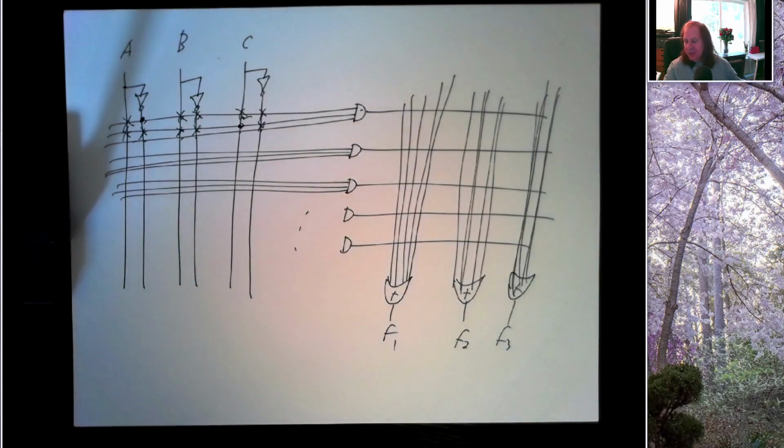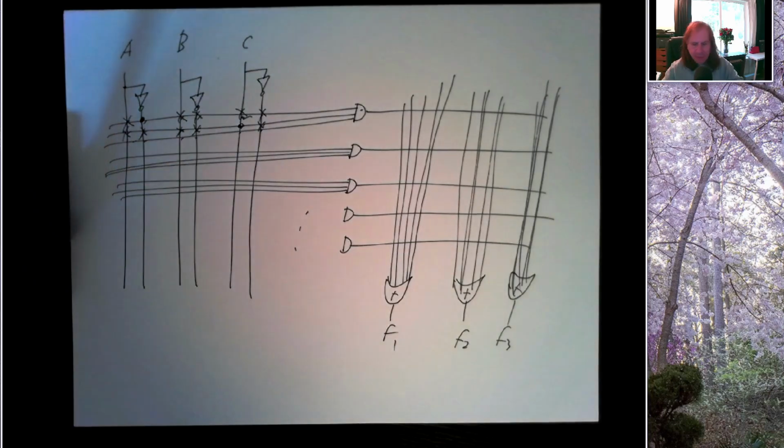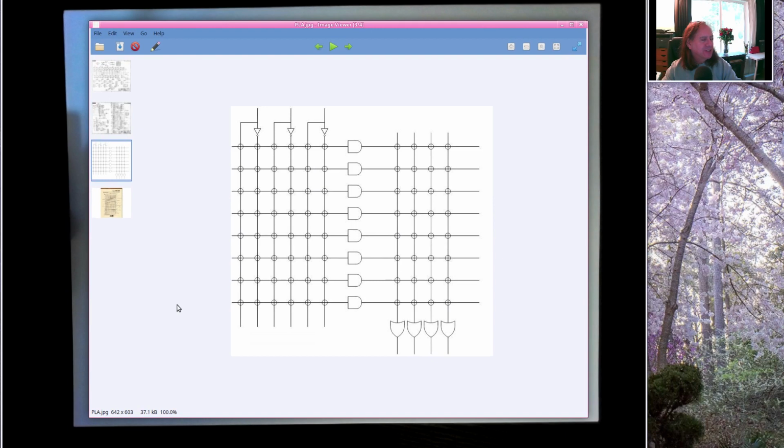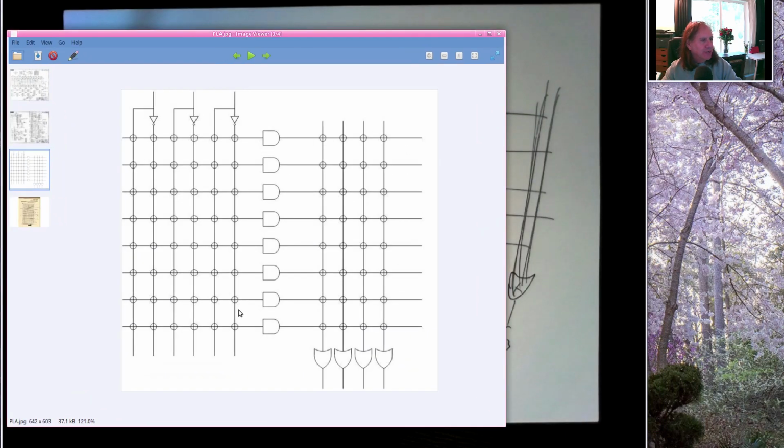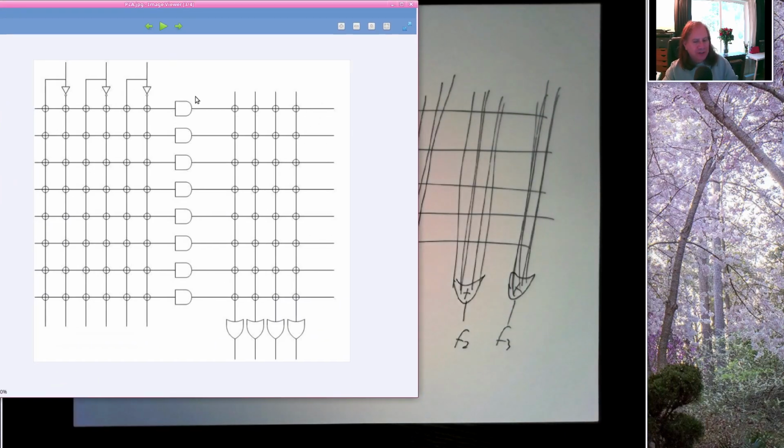So this is the essence of programmable logic. When we work with programmable logic, we'll see drawings such as this, where we show our gates with a single input instead of multiple inputs. I've got 3 lines coming in as inputs running vertically and 3 inverses, so I'd probably want 3 inputs to the AND gate. But for the sake of drawing this as what we call a fuse map, a way to see which connections are being made, we just show a single input to this, and we understand that